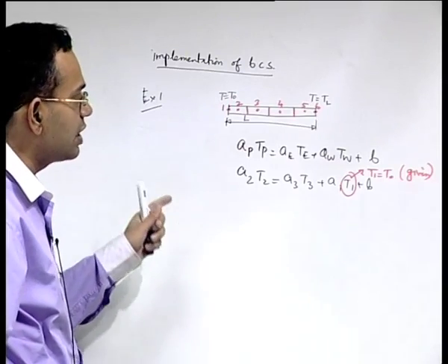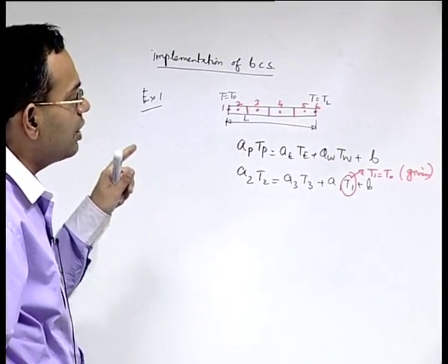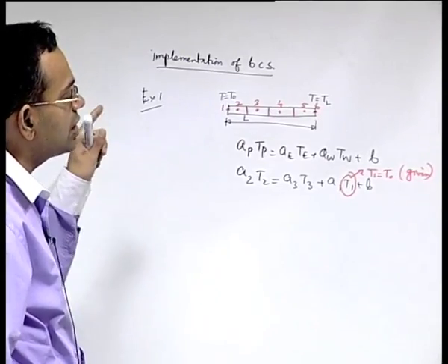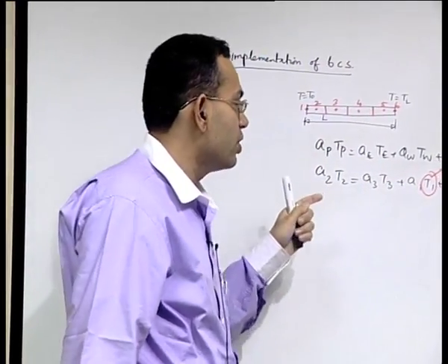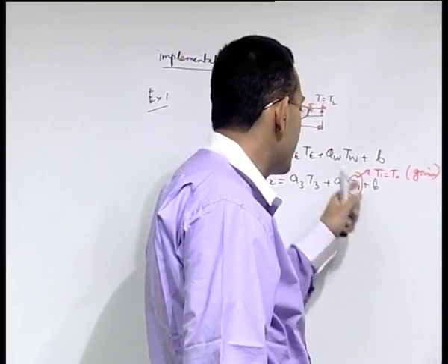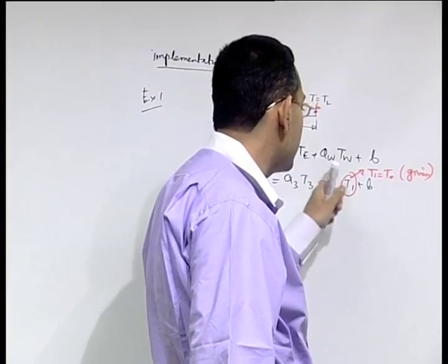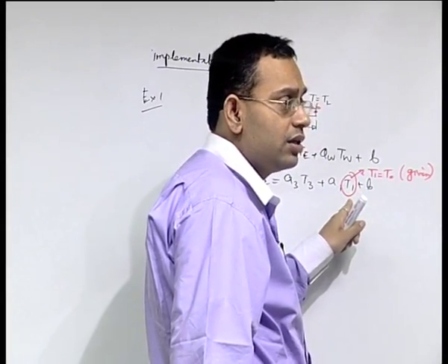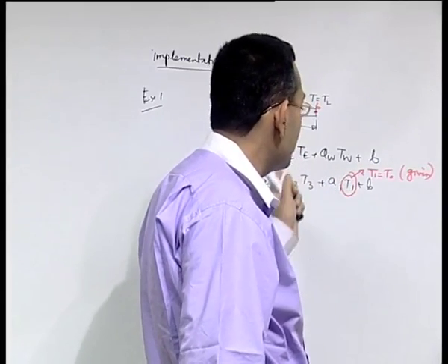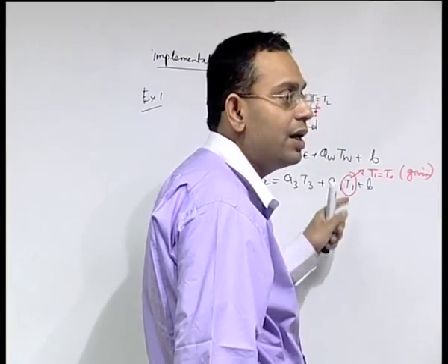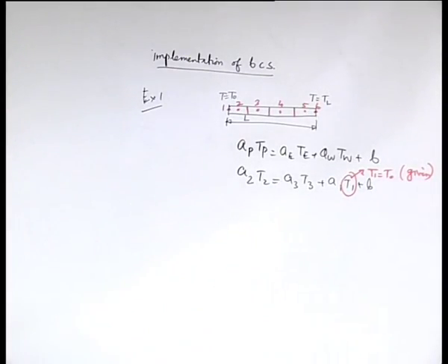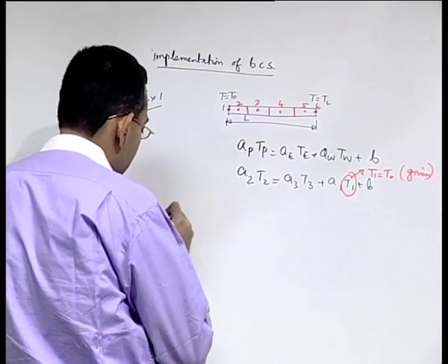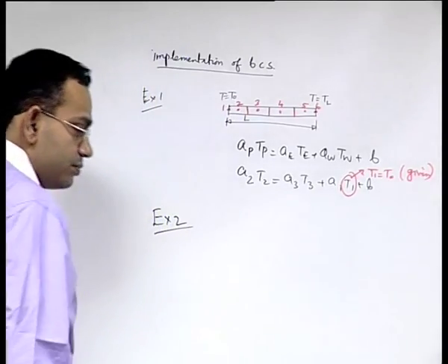We will not discuss this case in more detail because we have learnt by this time that imposing a constant temperature boundary condition is very trivial. Either you enforce its value specifically at the locations where it appears in the discretization equation, or you write the discretization equation as it is but enforce its specific value by using the penalty approach. So, you can follow either of these two ways. More interesting will be the other types of boundary conditions that we will consider with the subsequent examples.